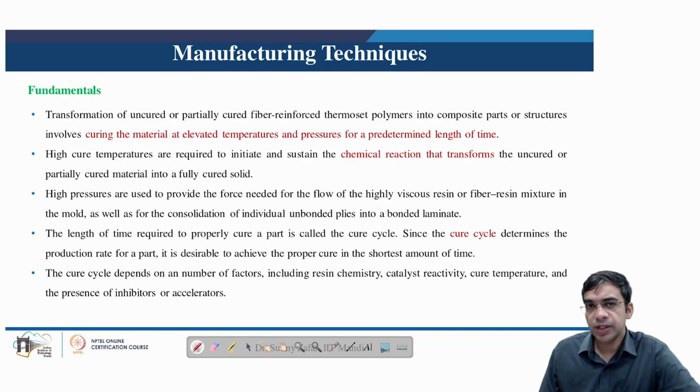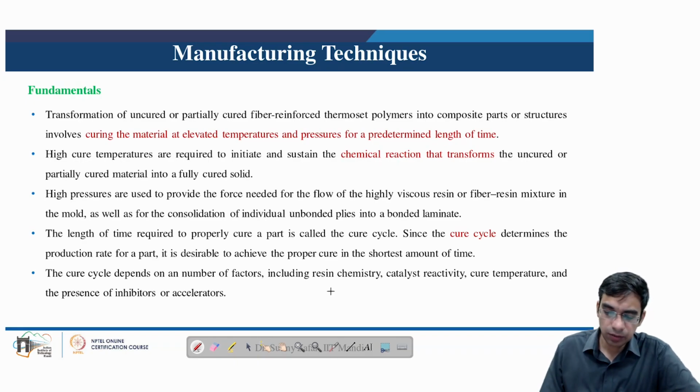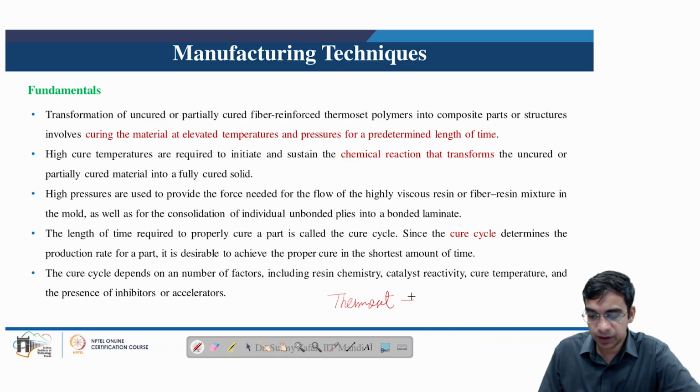In that thermoset also we have seen that the thermosets are more popular because they can be having permanent crosslinks, and in thermosets also we have seen specific thermoset, that is epoxy based thermosets are more popular because they do not generate any byproducts, and they have good fiber wettability, and their handling is also much better.